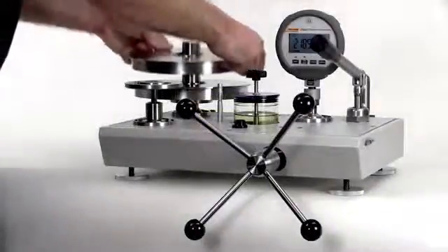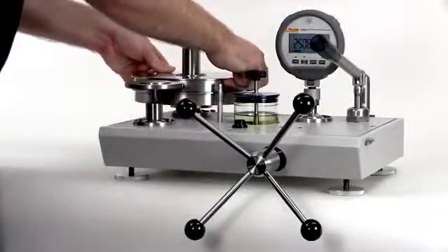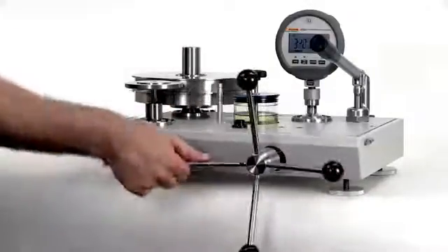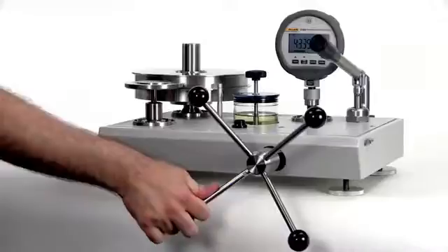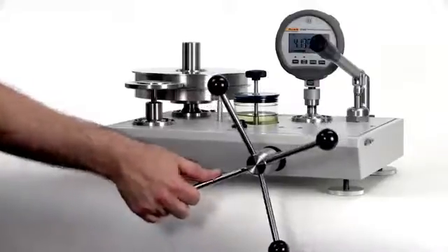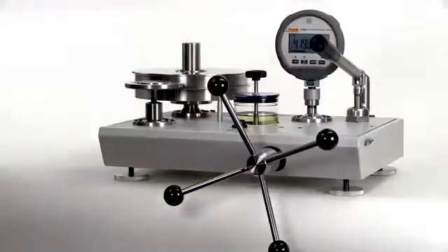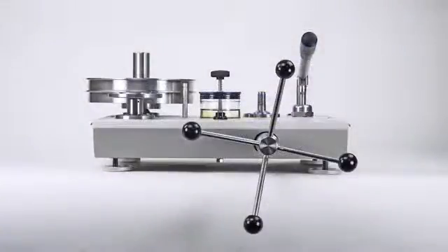Certain steps were taken in the design and manufacture of these deadweight testers to ensure that this specification can be met without additional calculations by the user. At the time of manufacture, the amount of mass required to generate a given pressure at the customer's gravity is calculated. The masses are then trimmed to this value. Without this trimming, the user has to do some level of calculation. The concept of just adding up the pressures on the masses is completely destroyed. Therefore, Fluke Calibration performs this trimming at no additional cost to the customer.